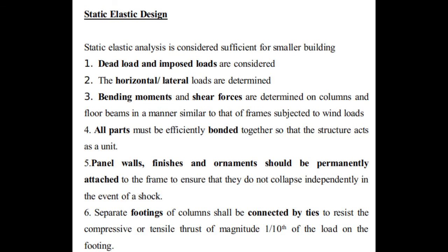Now finally, let us discuss the design approach of the earthquake resistant structure. There are 2 methods. Number 1, the static elastic design method, and the second is the dynamic design method. The static elastic design method is considered for smaller buildings. So let us look at the points. Number 1, dead loads and imposed loads or live loads are considered. Number 2, horizontal or lateral loads are also determined.